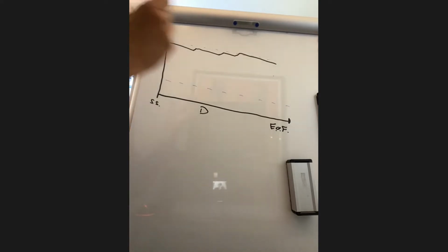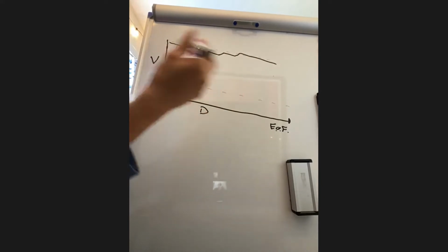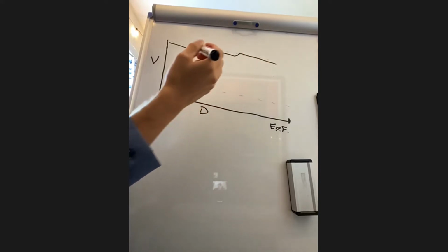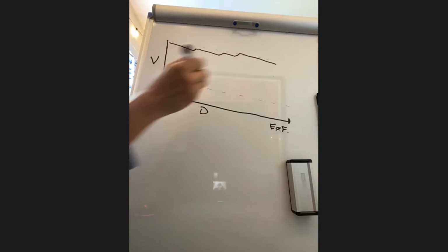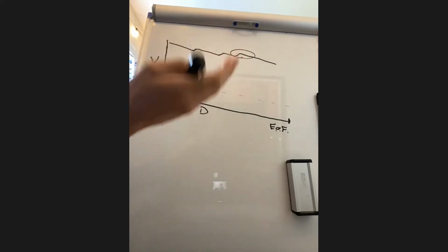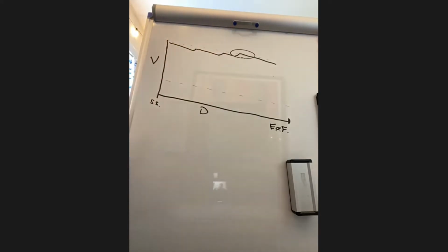And if you have situations where a circuit just goes gangbusters, to use an old term, on installing solar, you can see the voltage creeping up and up and up. And then here you have a situation where during this spring day, you now have a voltage violation. Voltage is now 128 or 130 volts or something like that, when the maximum that you were allowed to provide was 126.